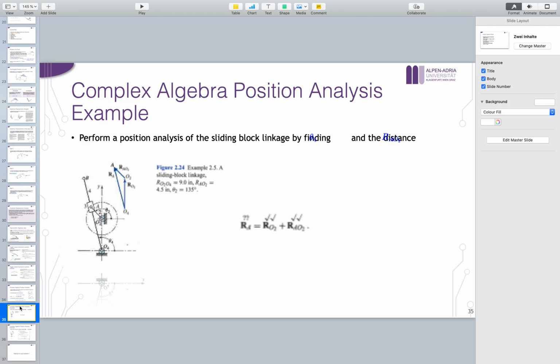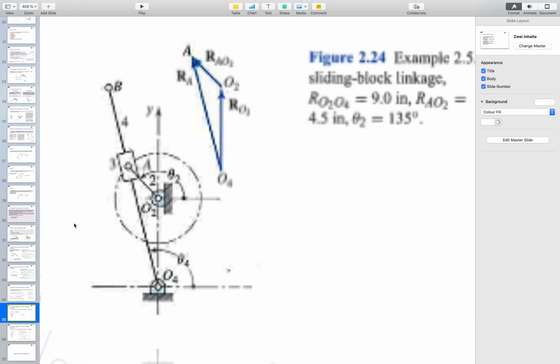Let's have now another mechanism there. We have here frame, link, okay? And of course, this is a closed mechanism, it has 1 degree of freedom, and if I move this down, then it will drive the rest, which means this would slide and this would rotate. Or also if I rotate this, then this would slide and this would rotate.